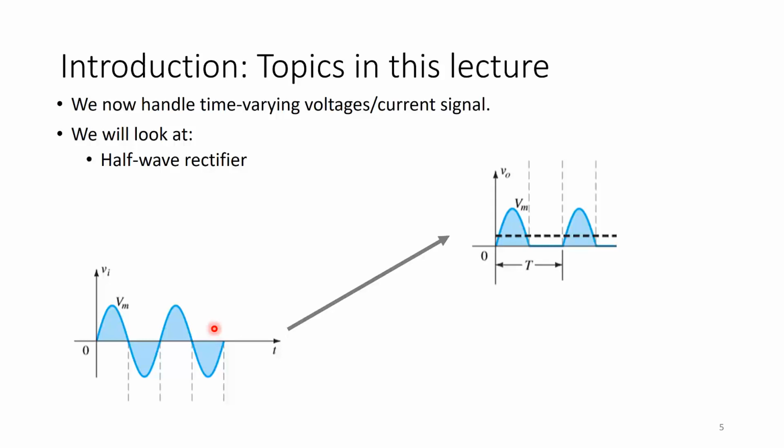The word rectify in English means putting something right. But here, there's nothing wrong with an AC. It's just saying that you want to put it in one direction only, unidirectional instead of alternating direction. So if it is a half-wave rectifier, whatever is in the negative cycle, the other part of the cycle that we do not want, is just omitted.